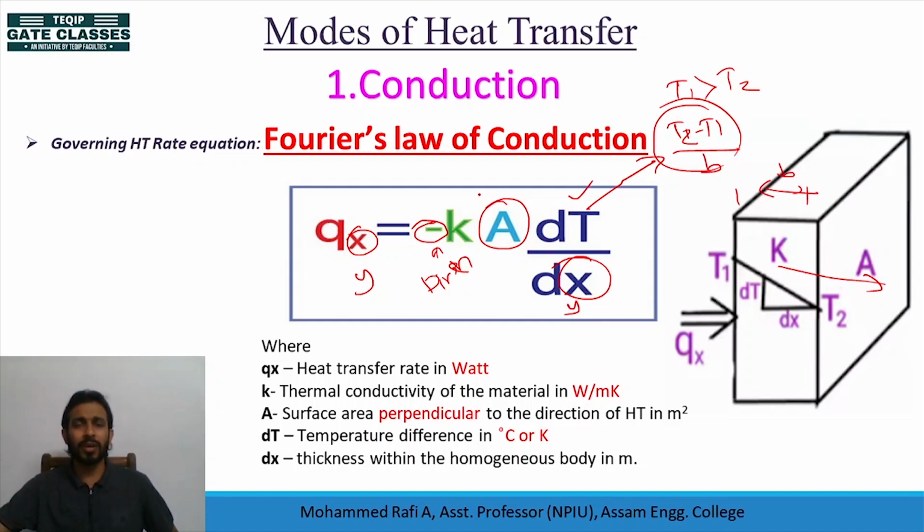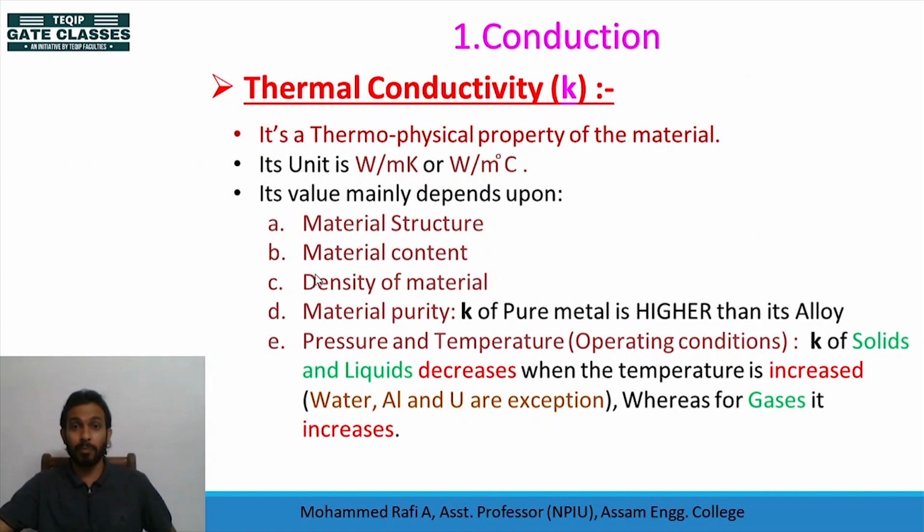But heat transfer cannot be a negative value, because heat is flowing, right? So in order to make the analysis easy, I am intentionally putting a negative sign, which doesn't have any relevance other than denoting the direction. Throughout our discussion, whenever you are dealing with the heat transfer rate, take it as a positive value. Now move on to another very important aspect regarding conduction, the proportionality constant,